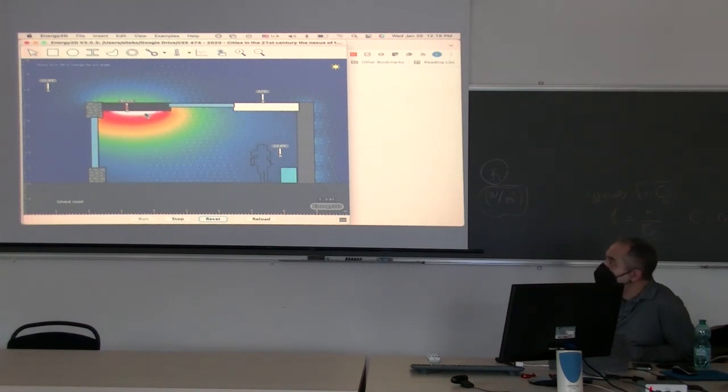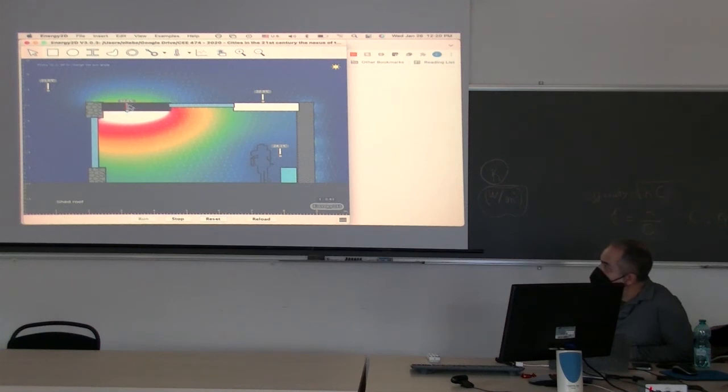And on the bottom it absorbs more, and also on the bottom, this is kind of a closed space, so the temperature is higher, and there's very little advection. So basically the inner temperature goes much higher than the outer temperature, because there is no advective cooling. You can move this thermometer up here. You can see that it's 32 on the top and 55 on the bottom, because on the top you have airflow that's basically cooling the surface.